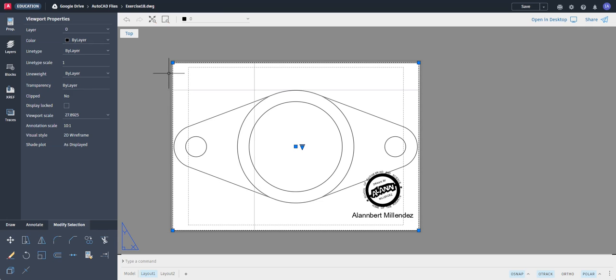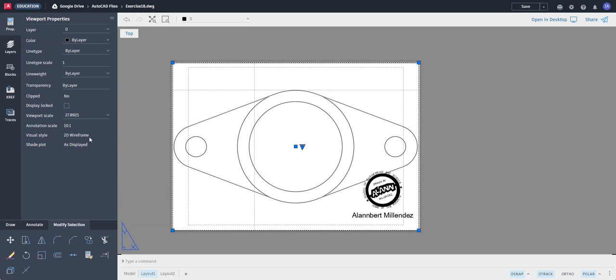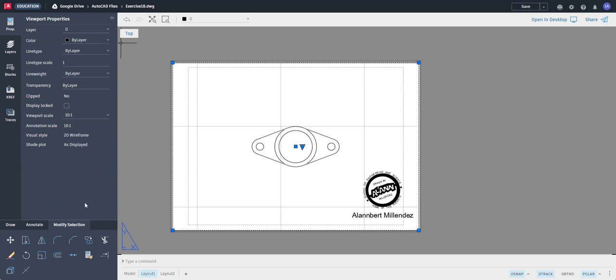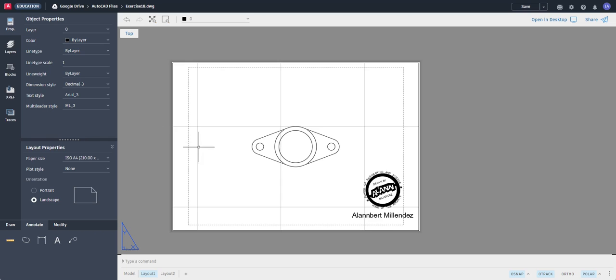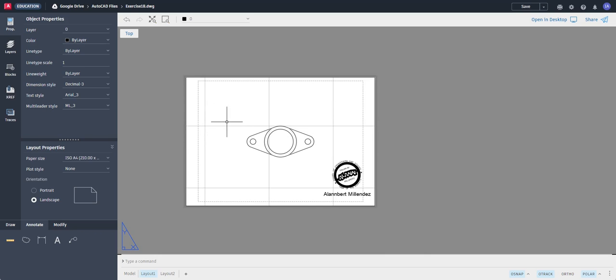Okay, and once that's selected, over here under property, you should be able to select the correct scale, and we are using a 10 is to 1. There you go, right? And then simply press escape to go out. So that must be the correct scale. Remember, if you change your scale by zooming, by entering and then zooming in and out while you are inside the paper, it will change the scale. So make sure you don't do that.